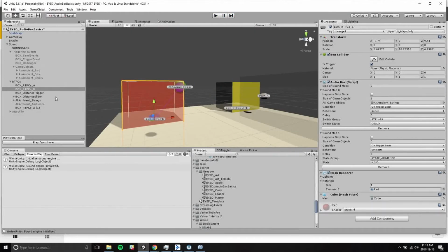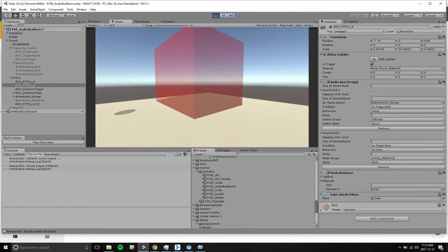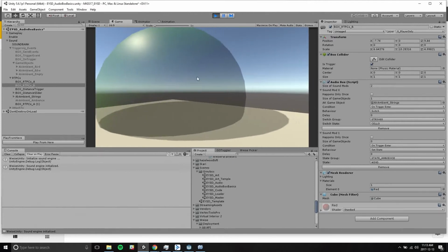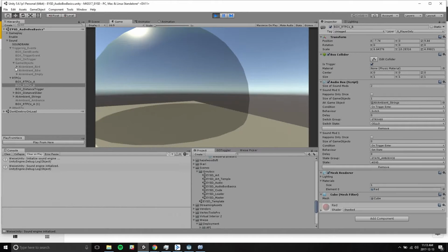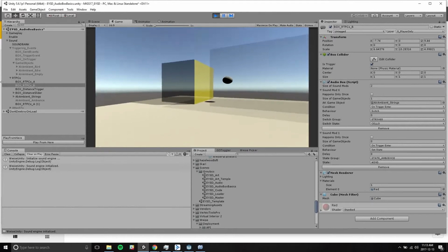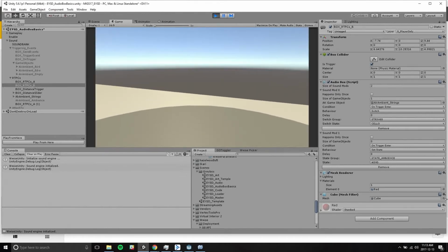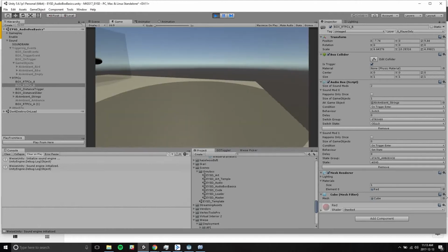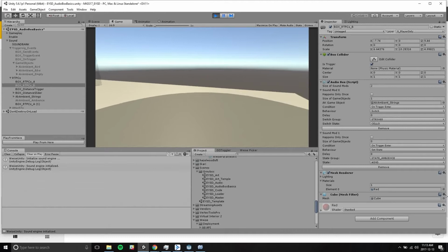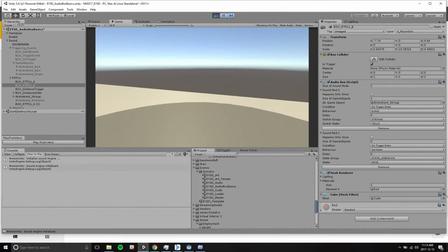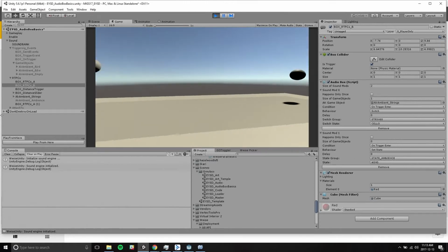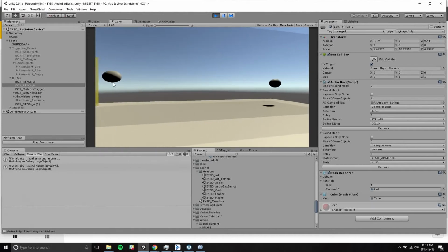And now what we have over here is, actually I'm going to stay in play mode to demonstrate this. I have over here a sphere collider. And the sphere collider is really interesting because it's controlling a parameter. And that parameter doesn't have any kind of lerping or slew rate set up in Wwise. It's based entirely on player position relative to the radial center of the circle. And I can also do that with this. This is a very similar structure. This is a distance slider. So it's a matter of the parameter being basically laid out over these 2 points right here.